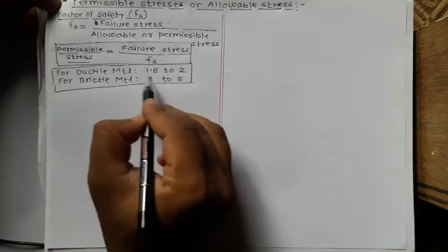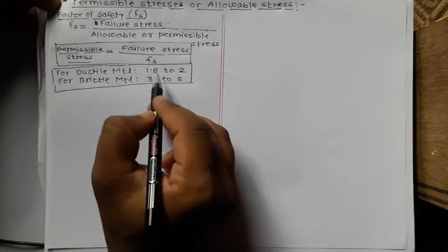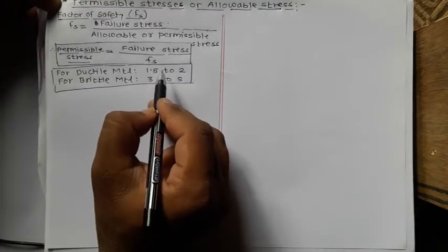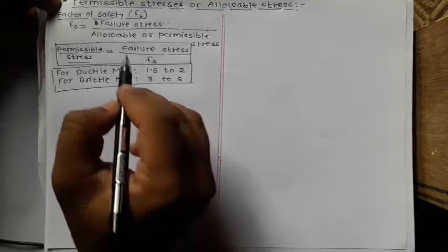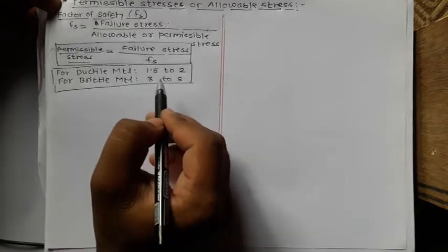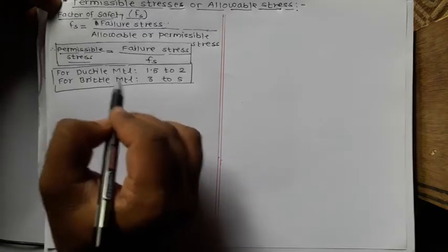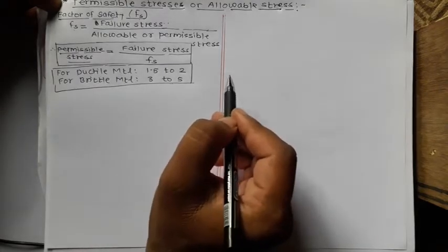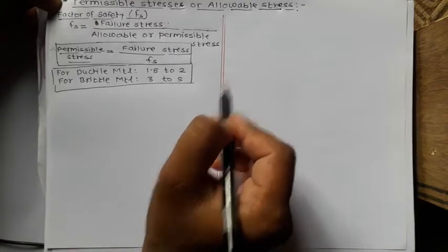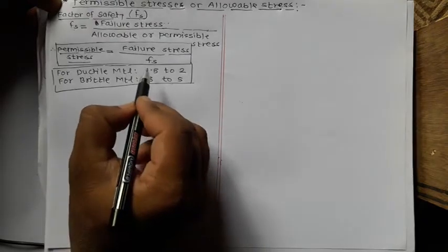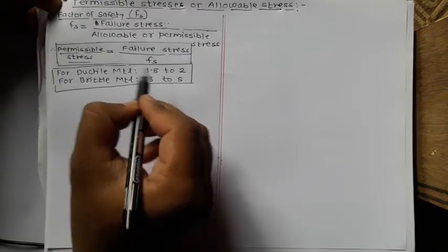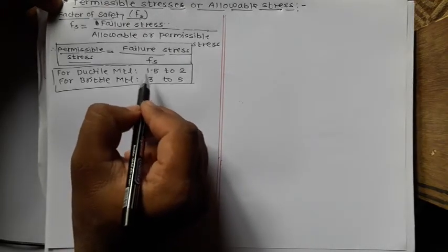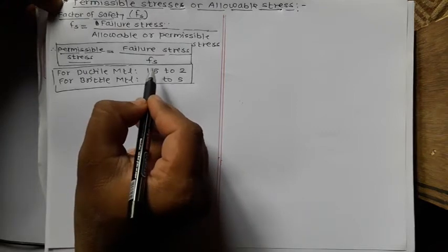Now these are just guidelines given for the designers, but you can change these values depending on the safety required. For example, consider the bearing: if you want to design the bearing for a simple machine, which is used for just simple machining operation, and similarly if you want to design the bearing for an aeroplane. While designing the bearing of a machine, you don't need more factor of safety, because if the bearing of a machine used for general machining fails, you just need to replace that bearing, so it will require just maintenance time and maintenance cost.